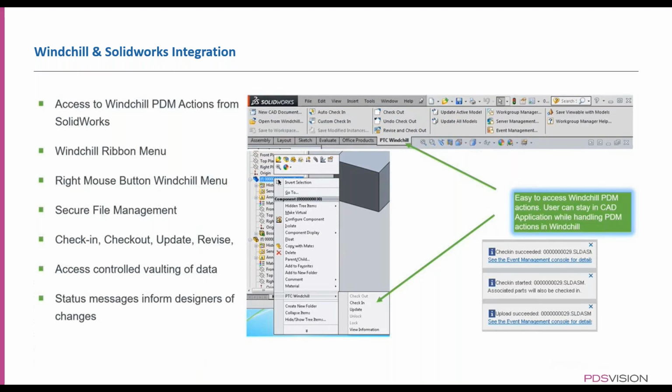So the Windchill system itself has got a couple of components to it. One of them is the database. What it does is, in the database, be it SQL or Oracle database, it will store only the metadata about the Windchill components, and then the actual files, the actual drawings, the actual SolidWorks files are pushed into what we call the Vault folder, which is a physical folder on the server.